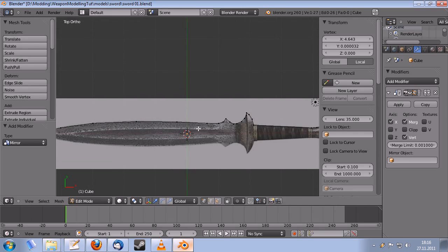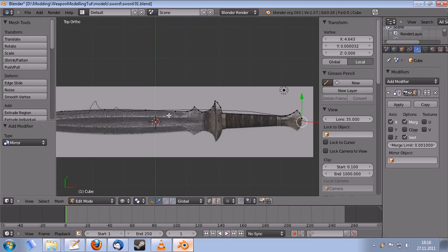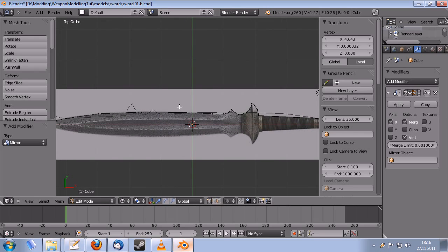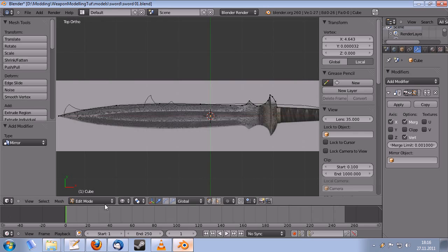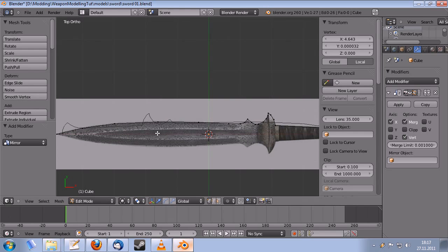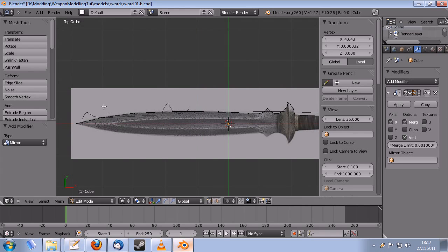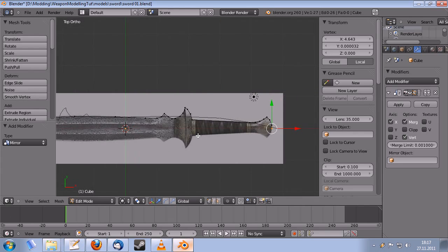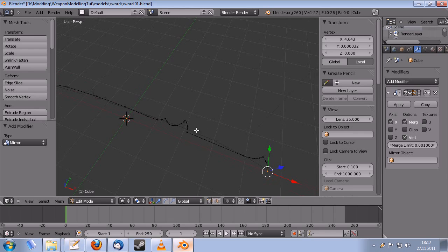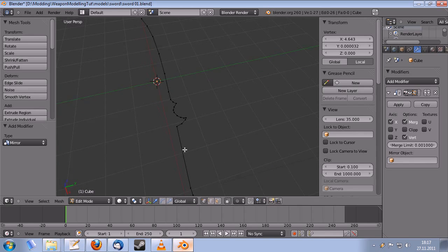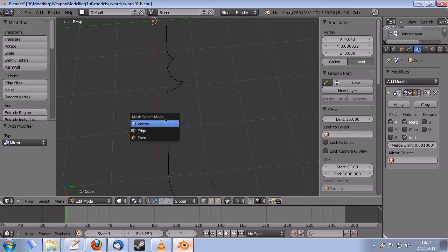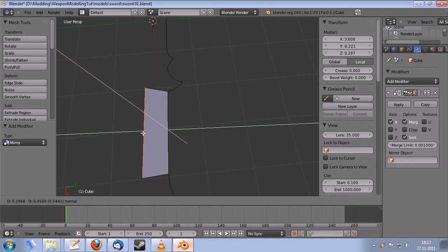well, we can actually change the display mode to wireframe by pressing Z or selecting wireframe down here, which causes us to see all the lines, and now we can see the mirrored lines down here. The difference between wireframe and the default solid mode is once you have faces, you can select an edge and extrude it to get a face.